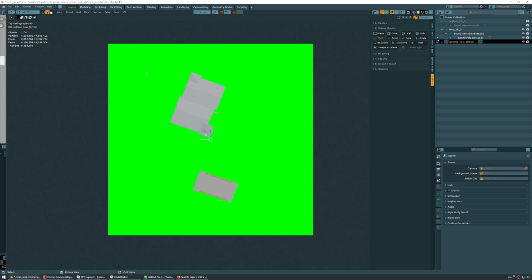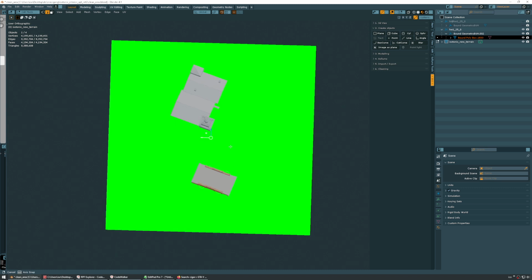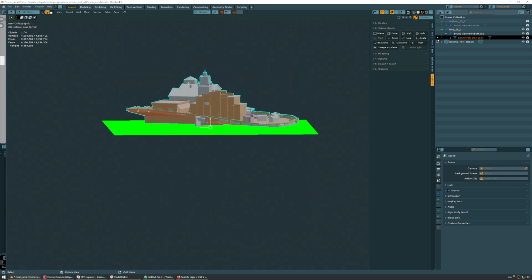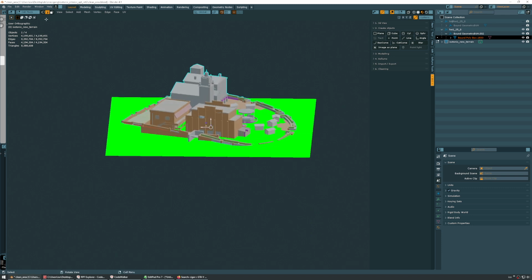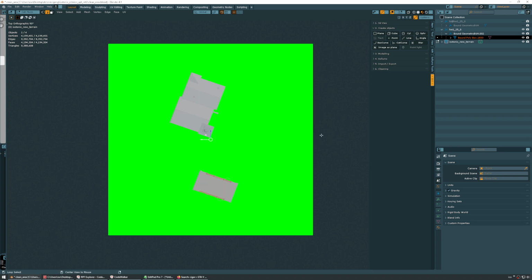And then with this in edit mode, select the building. So you have both selected. As you can see, the outline of the building is in blue, but you're still in edit mode with the terrain selected. So go back to top view, hold Alt and middle click so it shows orthographic 90 degrees, and then you go to mesh, knife project, and let it do its thing.